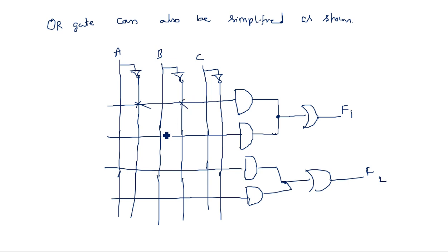So depending upon the connections, we are connecting like this, whatever it is required. I'm just randomly drawing whichever is required. So they are connected like this, and the corresponding product terms are added up and produce the function F1 or F2. Okay, this is the way of designing a programmable array logic using this AND or invert logic.